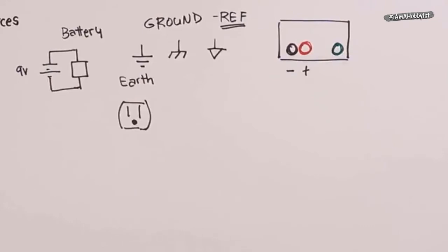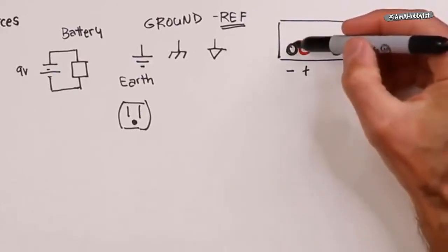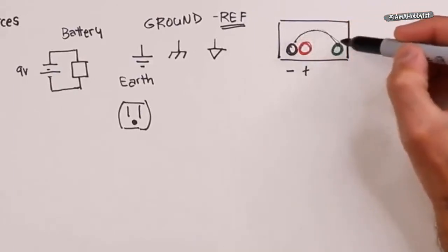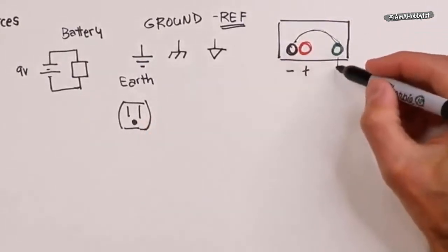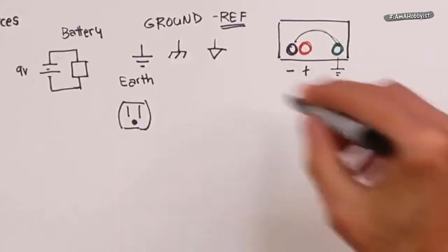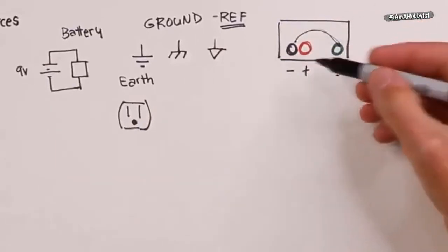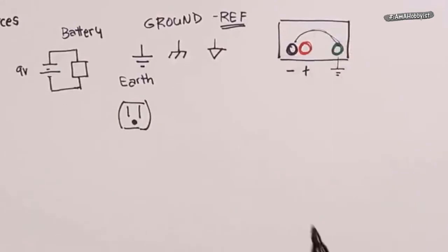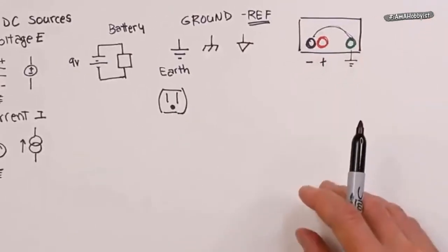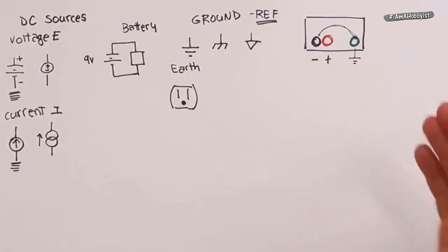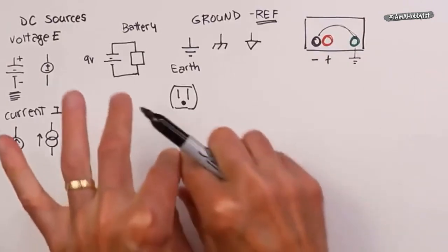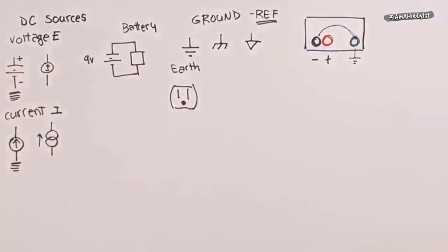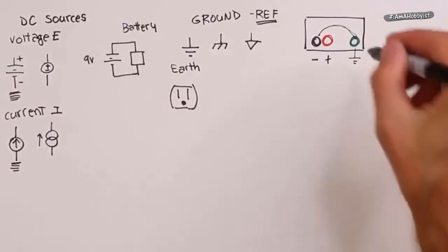So you don't have to hook this thing up to true earth. If you need to, you just get a little jumper that goes from here to here. You either do it directly here or on the circuit board. But that's only if you really need a true earth ground. In lab, typically we don't need to do that. This thing can be floating, like your cell phone, or imagine the electronics on an airplane. That wouldn't be very practical. You have a 7-mile long piece of copper wire draping across the ground? That's not going to work too well. Okay, so that's what we're looking at there.